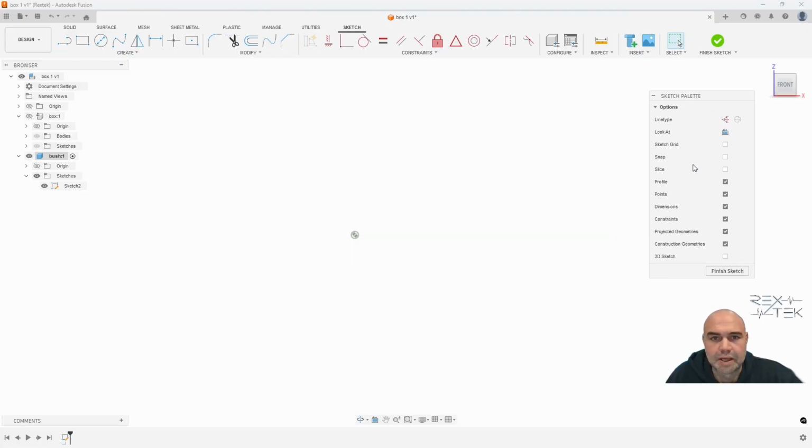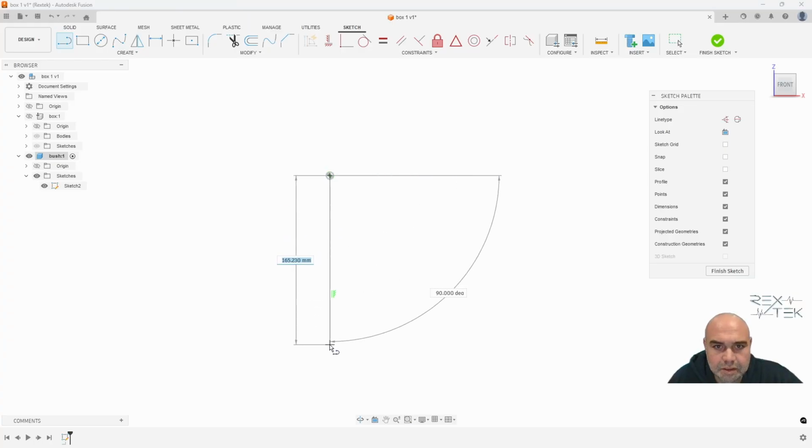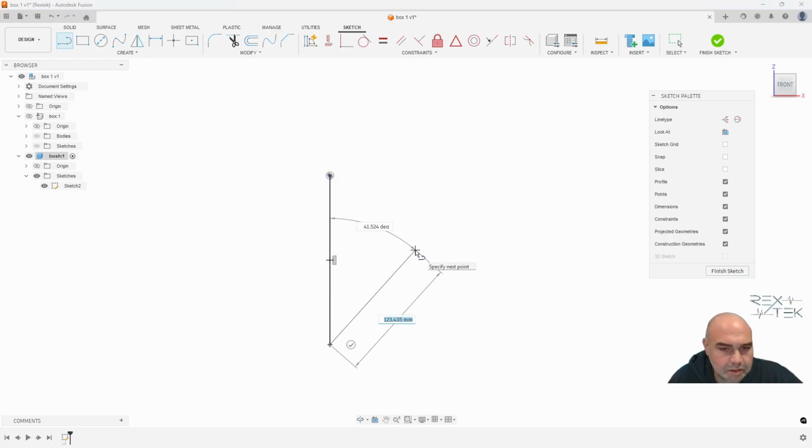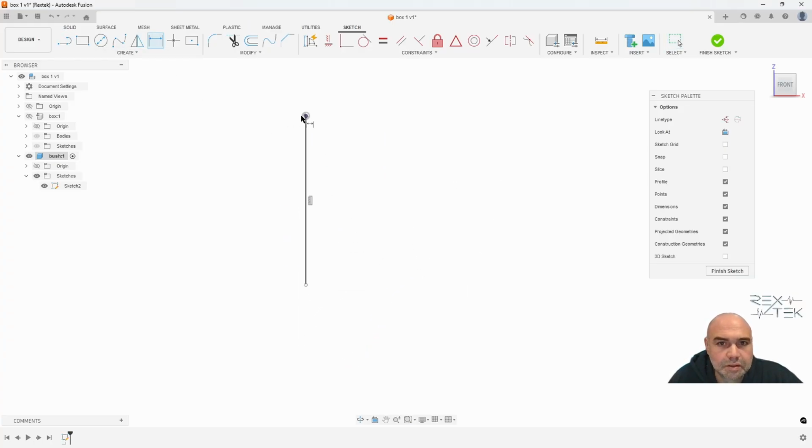When you open a sketch, you have this field, which is your tools that you can use in your sketch. So we are going to use a centre line because we're creating a turned, a revolved part. So let's say that's 150mm tall. I'm going to select the line and then select centre line.